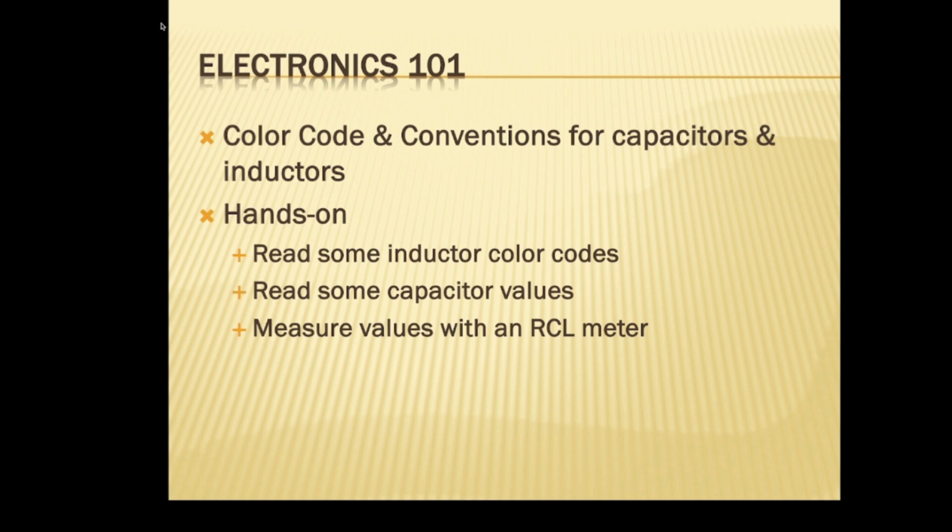What do you think, crew? So is it just a coincidence that mine seems to be that? So we're saying blue is the first digit, is that right? Okay. How do you know which way to orient it first? On these, generally the gold, silver, or black is going to be at the bottom, or to the right.